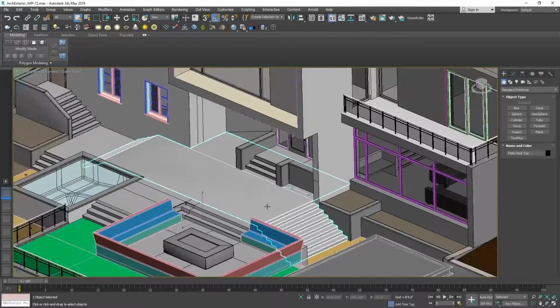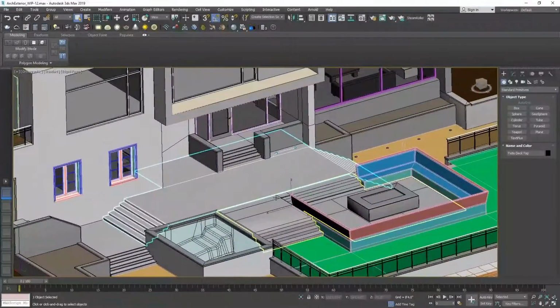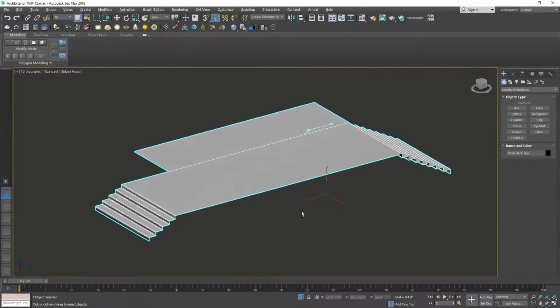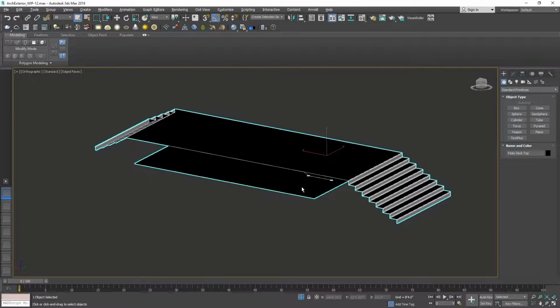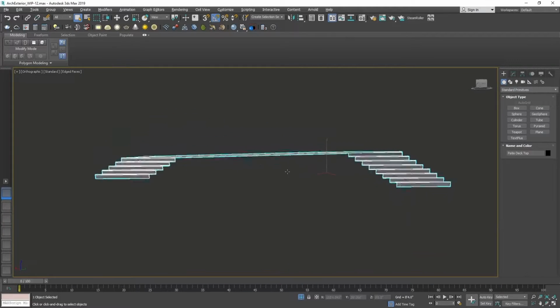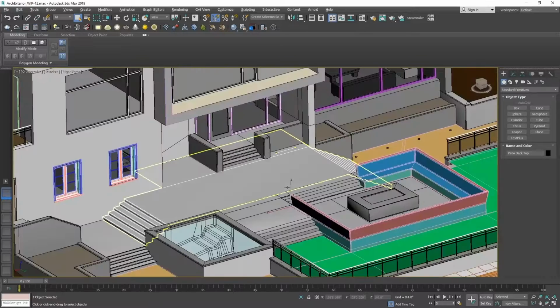To give us even more resolution to work with for our light map UVs, all of the back-facing geometry has been removed from the walls and floors. There's no need to include those faces if they'll never be visible to the user in Unreal Engine.